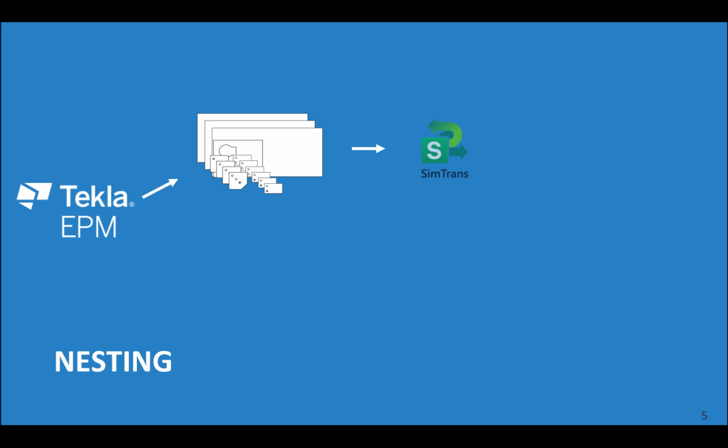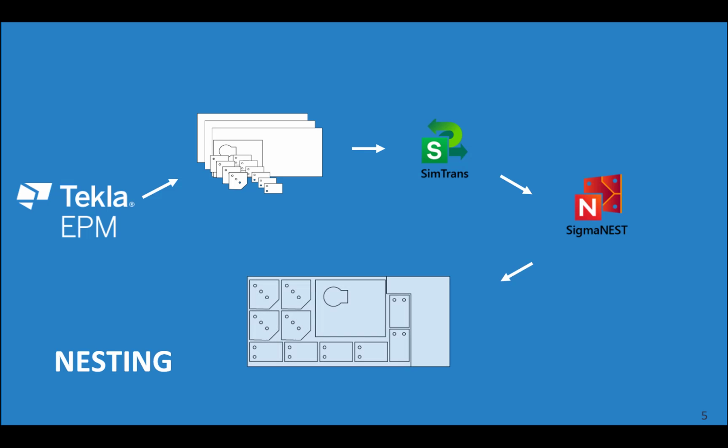The nesting process starts with creating a combining run in EPM. The parts are exported as a nesting request to SigmaNEST through SimTrans, creating a work order. In SigmaNEST, the parts are nested onto stock, either inventory or orderable. Then results are sent back to EPM so the material can be reserved or ordered.